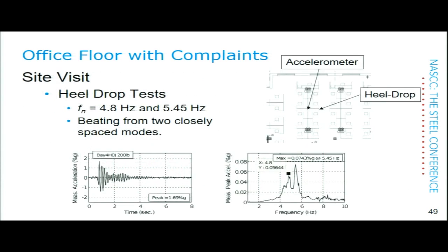Okay, so let's talk about our site visit. We went there, and I'll just zoom in on this one bay. This is a huge building with many bays. This is just one of them. We will talk about it only today. So we go to this bay, put an accelerometer at the middle of the bay, and do a heel drop nearby, like just off to the right there.